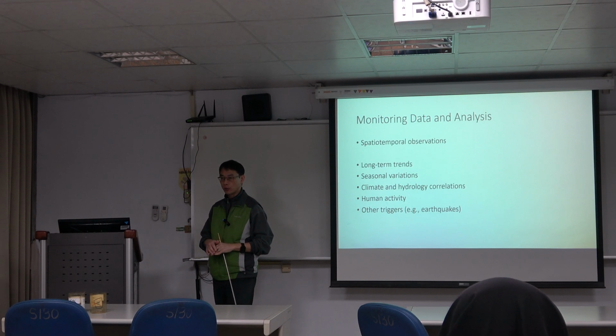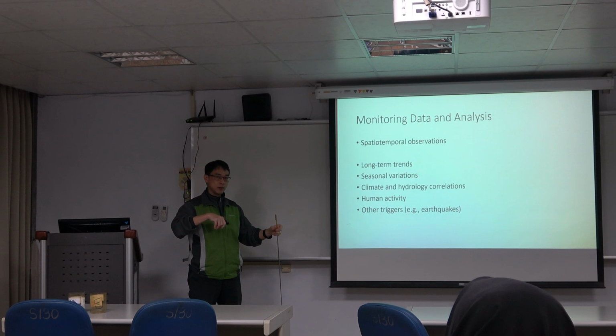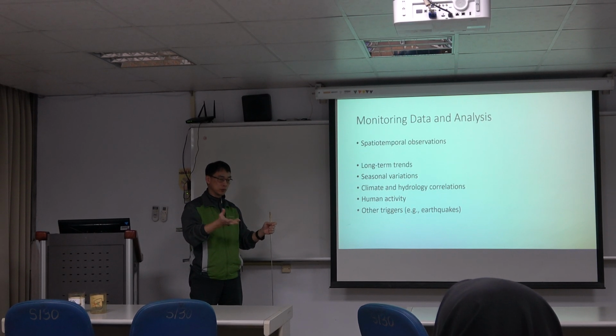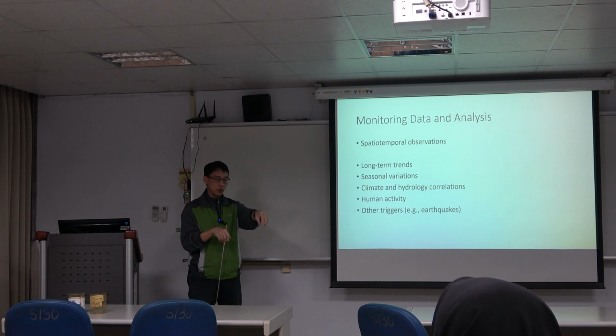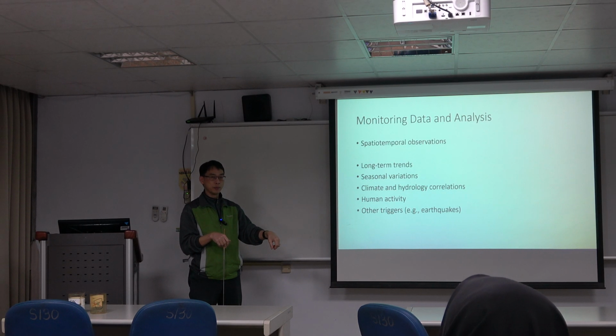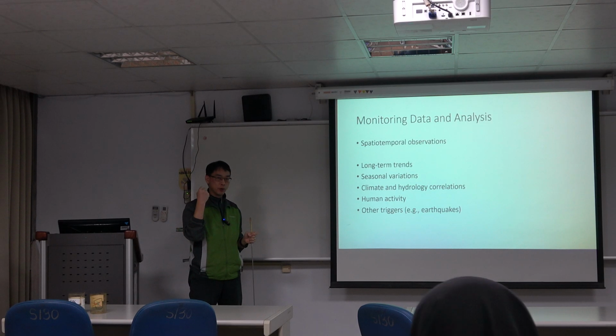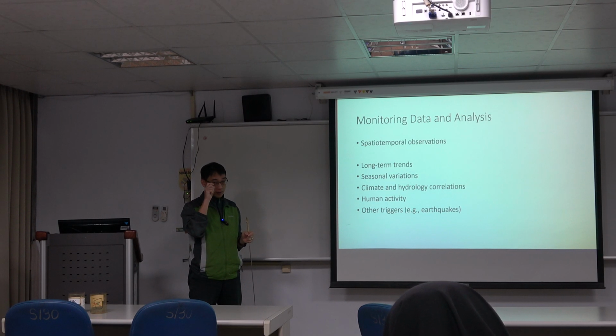Commonly, when you have a project or work, you go to the field, you need to decide how many points to survey. And the survey could be solid and also soft. Soft could be that you drill the borehole, and then you put the device inside to do the measurements for the water levels. And sometimes you might go there to take the water sample back to do the chemical ion analysis. Okay, so that will be two ways.